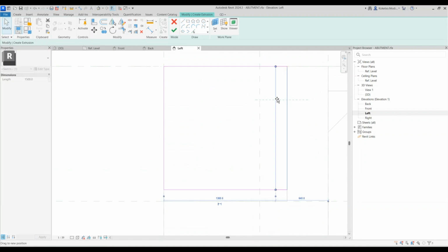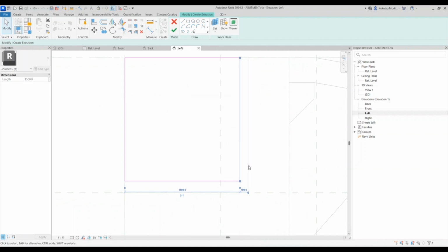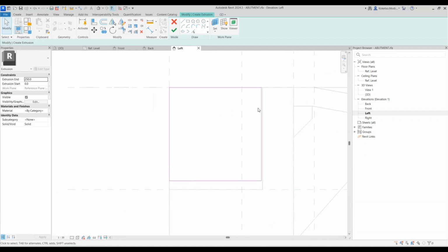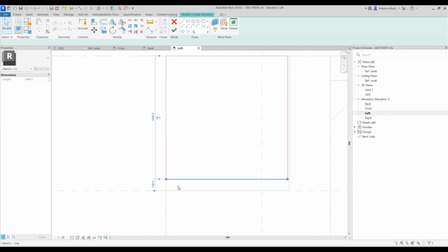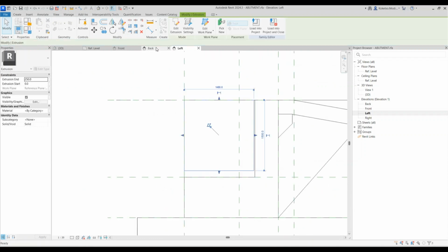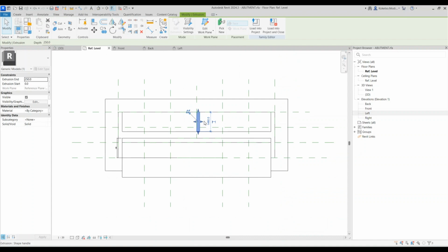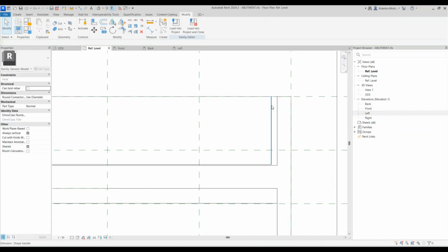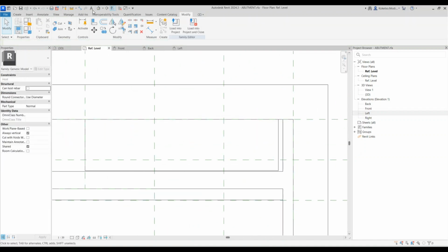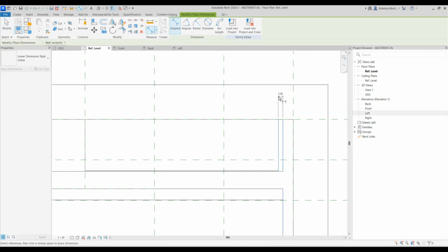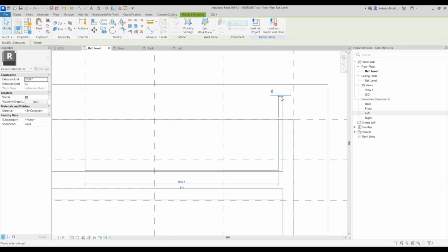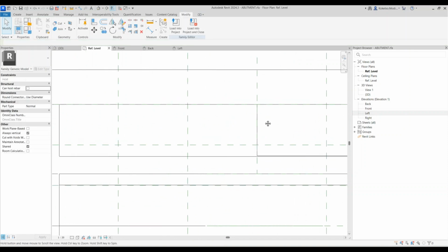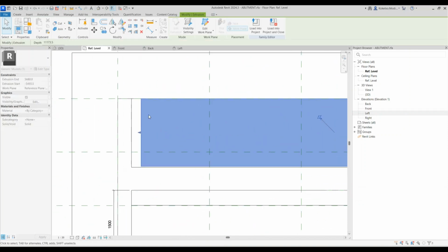Let me place a block like that. I'm going to offset it from the face of this wall by, let's say, 20 mils, and I think that's fine. And then this by 140, and then I'll say finish. I'm going to drag this towards the end, and from the end I'm going to offset this by 20 mils also, and also this side if I drag it.